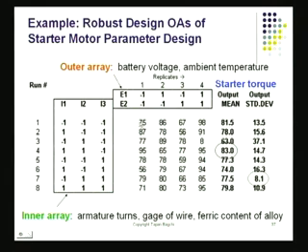They ran this trial and they made sure that while these results were evaluated, the motor itself, the prototype that you produced, was subjected to these noise conditions. So I took the same thing and I measured its torque at these different conditions. Under certain conditions, it gave me good torque. In certain conditions, it gave me poor torque. And I calculated the mean of these responses for each of the noise settings and also the standard deviation of the responses.